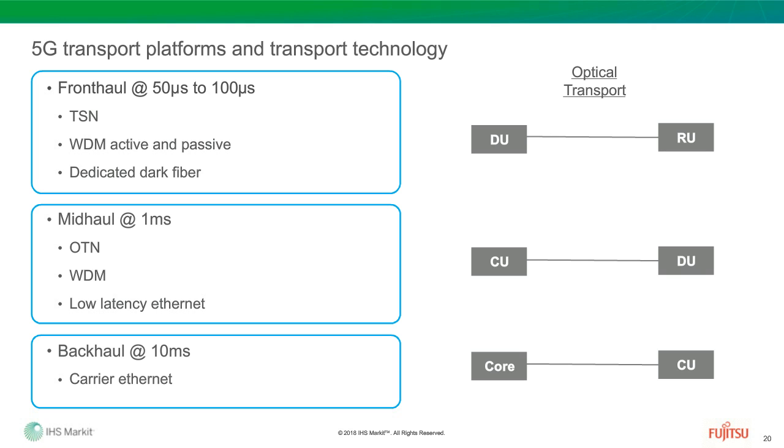A TSN transport MUX is a layer 2 platform based on IEEE 802.1CM, offering Ethernet SLAs with timing and synchronization to maintain fronthaul operation within the 100 microsecond latency maximum. Platforms capable of IEEE 1914.3 will also provide CPRI agnostic and aware modes to blend 5G eCPRI radio over Ethernet traffic with legacy 4G CPRI traffic on the same fiber path.